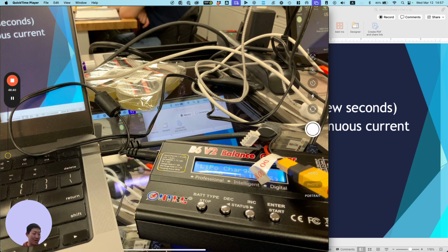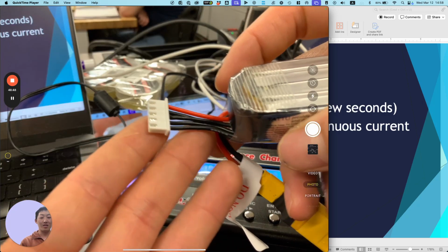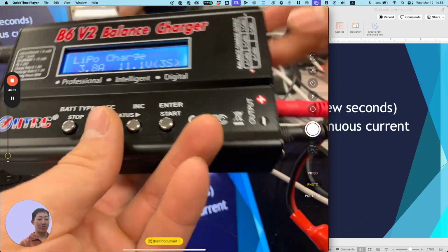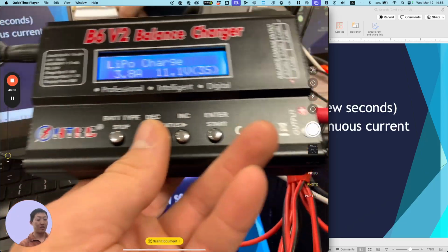And then the deviations are going to build over time if you keep charging it the normal way without regard to balancing. So when you're balance charging, you do have to plug in what we call the balance leads. You see right here. Otherwise, it's not going to work. Right now, I just have it plugged into the normal power plug.